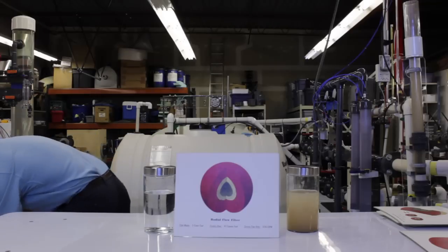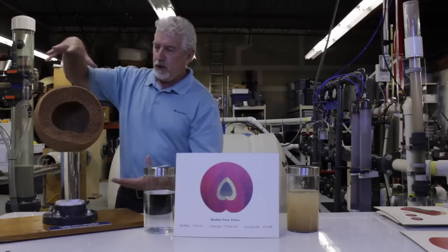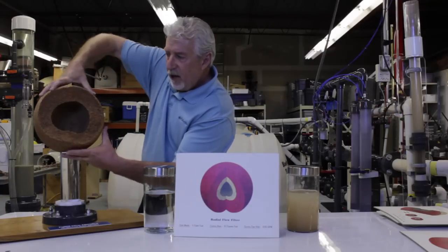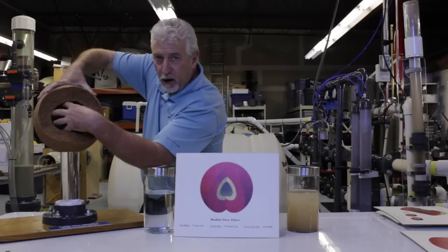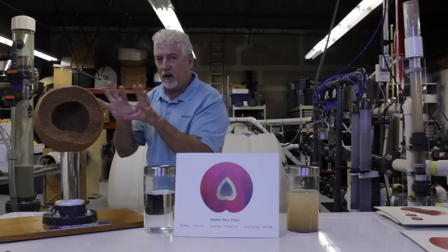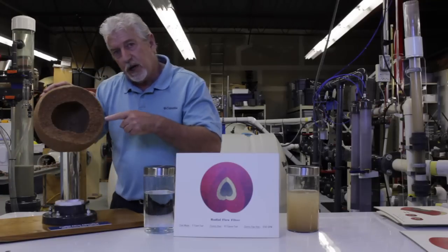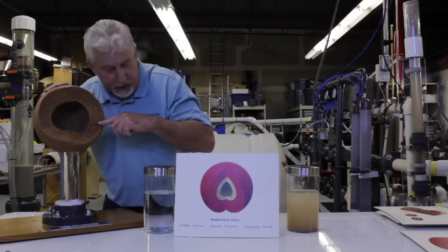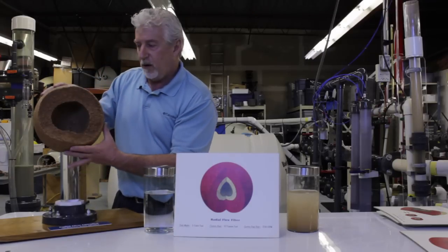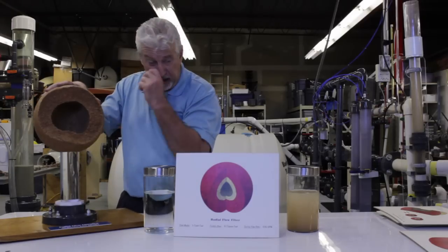It looks like this. Inside the machine, the granular media is in jail. It's captivated between 2 huge perforated hemispheres that compacted into another sphere that's smaller. So you have controlled bed depth, mechanically compacted. The incoming water comes in and envelops the sphere, 3 times bigger now. So you have 3 times the flow rate. And the filtration occurs on an accelerated flow path through the mechanically compacted granular media. It's collected at the inner drain and works better. No malfunctions. I just tripled the flow rate. I just tripled the appetite for contaminant.